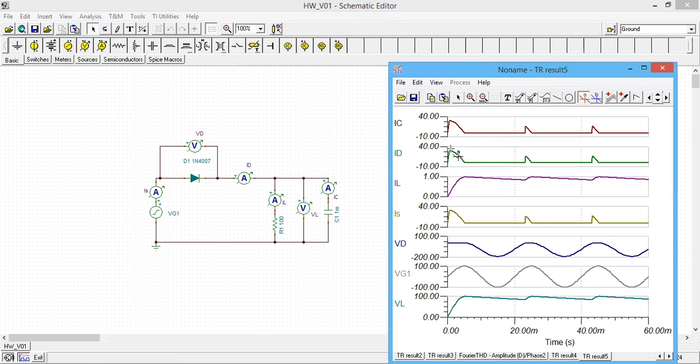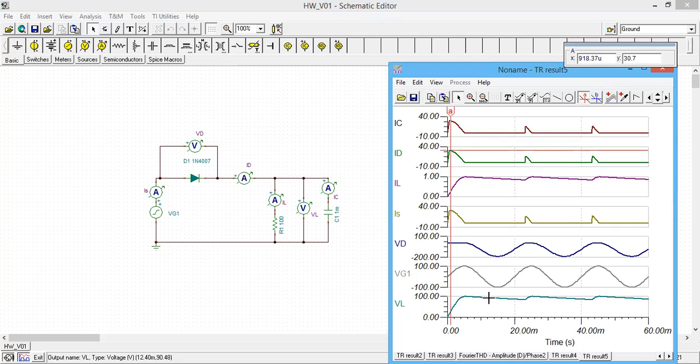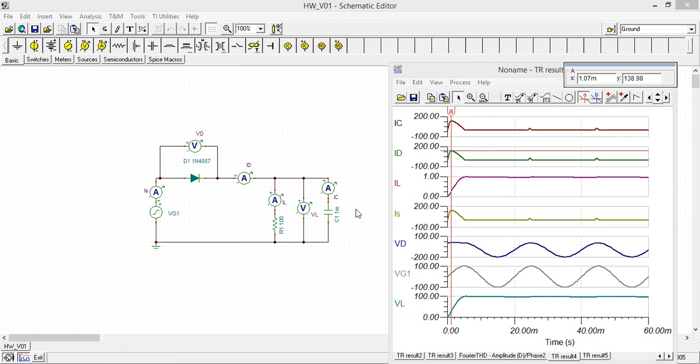now the surge current is almost 30, right? 30.7, which is acceptable, but there's a slight peak-to-peak ripple. If you are satisfied with this ripple, you can just use this diode. And if you want a flat DC line with higher capacitors, most probably you have to use a different diode model which can accept this kind of peak surge current. So these small things you have to be careful about. That's why the transient simulation is important.